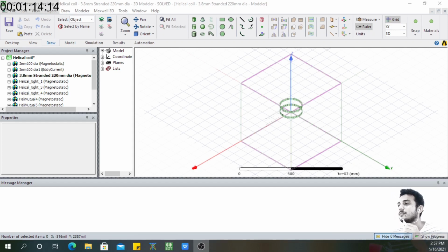So Simplorer, in simple terms, is like MATLAB Simulink, where you draw circuits and put blocks. It's very similar to that. We will build a very simple circuit, and then we'll check the coil-to-coil efficiency: how much power is wirelessly transferred and with what efficiency. So two things matter, right? How much you are sending in, and how much you are getting on the receiving side. That's a simple concept, and we will discuss more on this later as we do it.